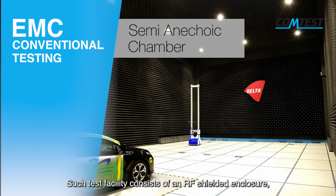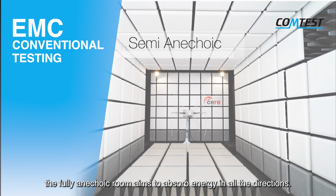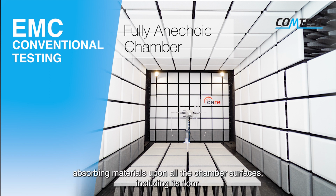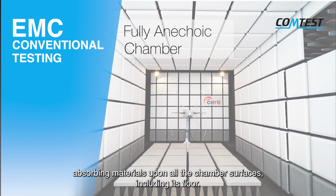Such test facility consists of an RF shielded enclosure which ensures cancellation of false signals from the outside world, and RF absorbing material on the inside, which dampen all unwanted reflections coming from its walls and ceiling. In contrast to the semi-anechoic chamber, the fully anechoic room aims to absorb energy in all directions. To accomplish this, the FAR concept implies the utilization of absorbing materials upon all chamber surfaces, including its floors.